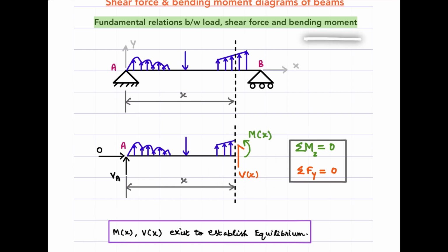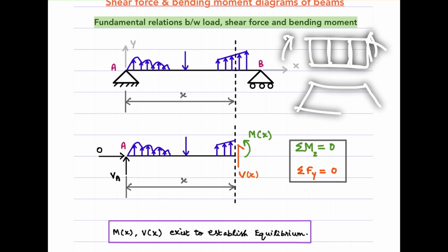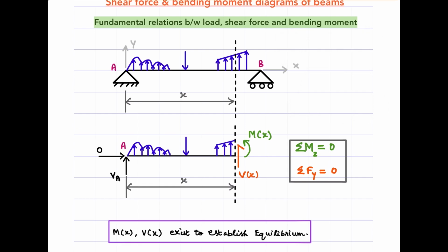Because we can construct a simple experiment using an eraser. Take an eraser, mark two lines on the top face. Now, if we flex it, what's going to happen? This is going to change its shape like this. Okay. Now, the two lines will become the ones we see here. If you consider what's happening to the lines, the top lines come close to each other, whereas the bottom lines will move farther from each other, right? So that's what will happen.